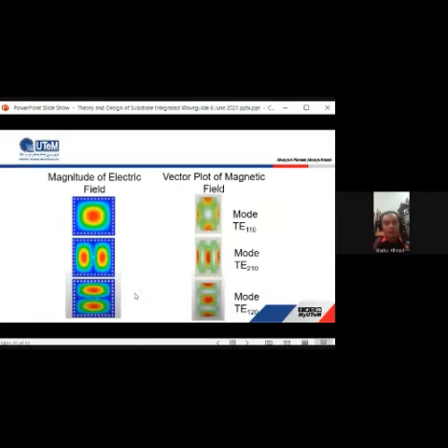For the cavity, the first 3 modes propagate, and the first mode is called the dominant mode. Typically, we can use this mode to excite an antenna. As you know, the bidirectional antenna is a very popular antenna to be used, but the unidirectional antenna is the most popular one. So we can use a reflector or cavity behind the slot, and straight away implement the SIW concept in a planar form. Okay, next.